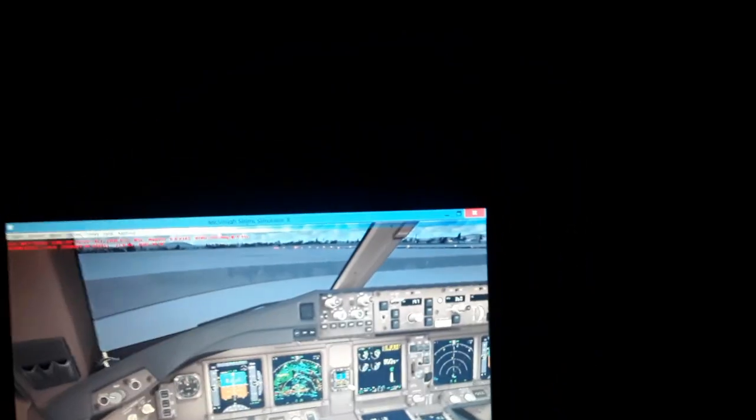We have on the primary flight display also the altitude indicator, the pitch ladder in degrees, and the bank angle in degrees. We have also the magnetic heading and track, the magnetic north pole and the true north pole, and the magnetic variation depending on where we are in the world. We also have the flight mode associated with the autopilot and the autothrottle, and later on vertical navigation modes. So I'm gonna show you then the navigation display. You can see here the navigation display.